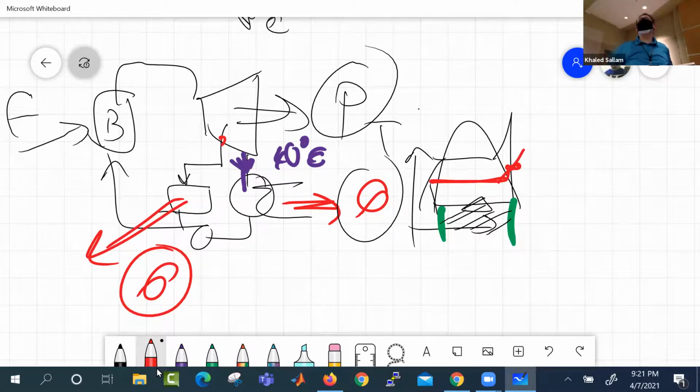Not only can I do more quality heating, since certain processes need really high temperature, but with this 100 joule at 100 degrees C, I can make work out of it. I can take this 100 joule at 100 degrees C, put a cycle under it and get work. But the 100 joule at 40 degrees C, that is garbage. You just throw it in the ambient. There is no more availability, right? Because it's already very close to the ambient.